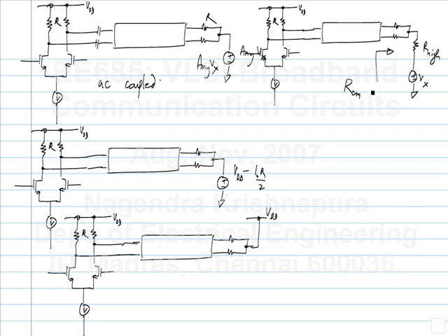Okay. So this is AC coupled, and then this is DC coupled with the right common mode, this is DC coupled to VDD, and this is DC coupled but with a high impedance. Okay. The common mode, this means that the common mode impedance is very high, right? It is R plus R high, R by 2 plus R high. Okay. So all of this is possible, all of this is valid, and all of this is probably used in some case or the other.